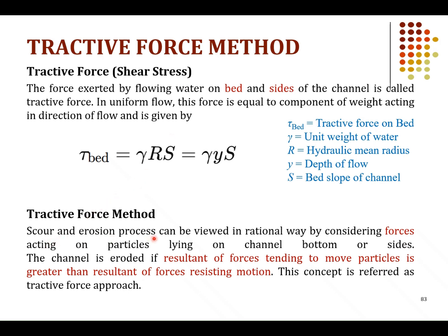Scour and erosion process can be viewed in rational way by considering forces acting on the particles lying on the channel bottom or the sides. The channel is eroded if the resultant force tending to move the particle is greater than the resultant force resisting the motion. This concept is referred to as tractive force.